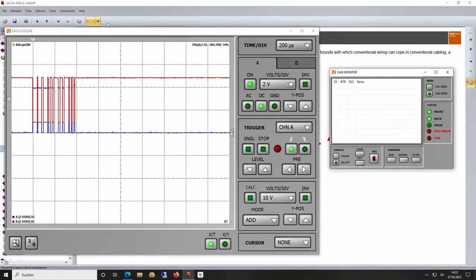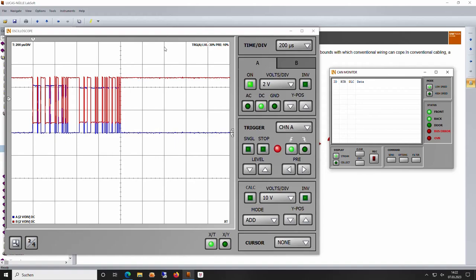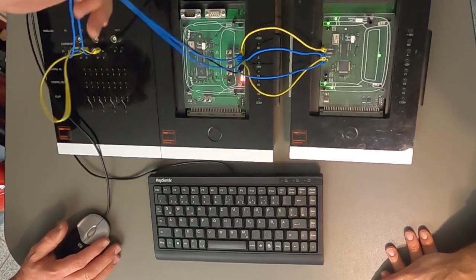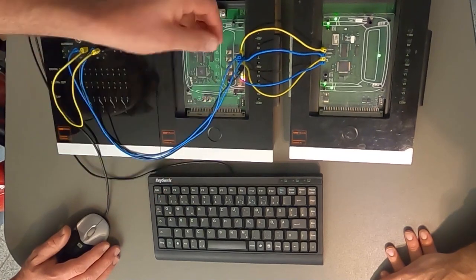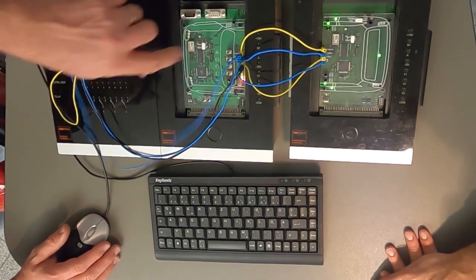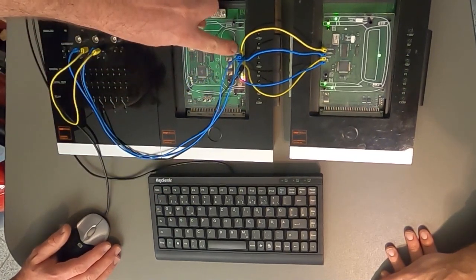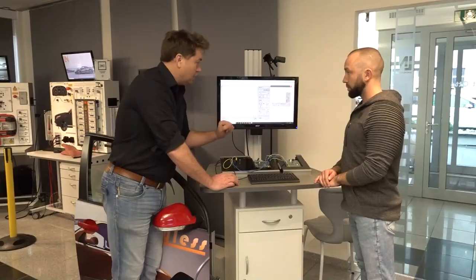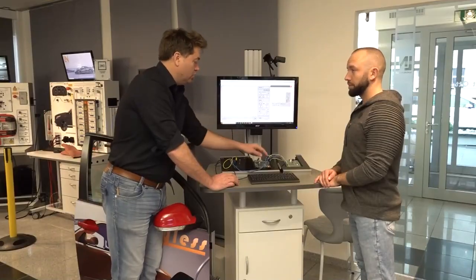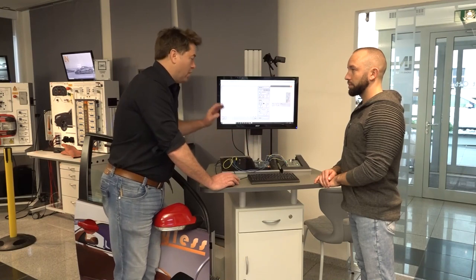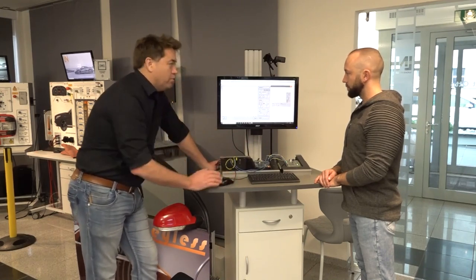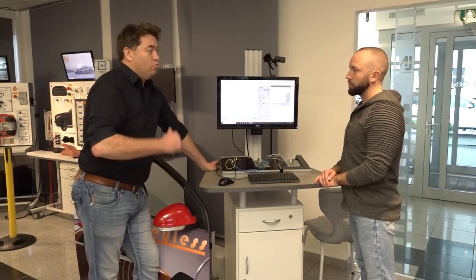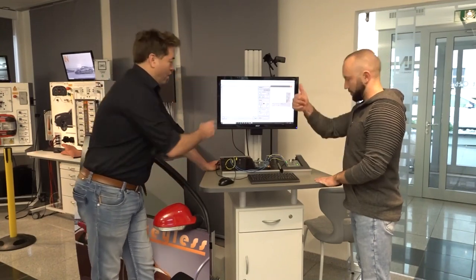So what we'll do is we'll just bring up our oscilloscope in this matter. So we have our 2-channel oscilloscope in this case. So we have channel A going to CAN high. We see CAN high written on here, but we can also see by reading the oscilloscope signal if it's CAN high or CAN low just by looking at it as well. CAN high, for example, I always like to say, is CAN wants to go high. So it's the one at the bottom.